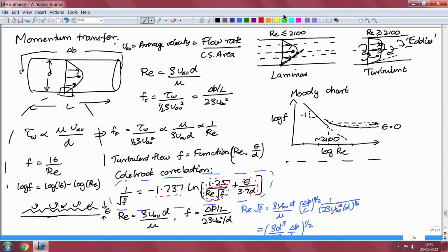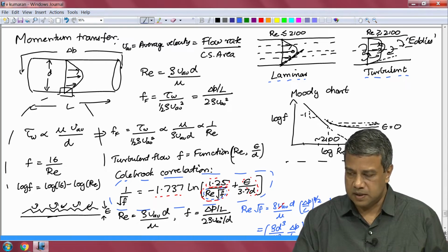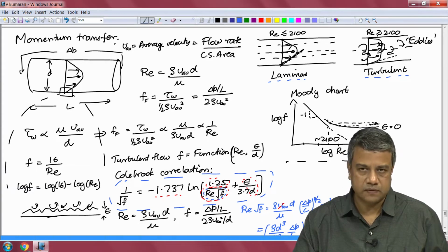In the last lecture, we were looking at the salient characteristics of the flow in a pipe. One of the central ideas here is the transition between a laminar and a turbulent flow. When the Reynolds number based upon the average velocity and the pipe diameter is less than about 2100, the flow in the pipe is laminar. In a cylindrical pipe, the velocity profile is parabolic and the streamlines are straight and smooth, and there are no fluid velocity fluctuations perpendicular to the streamlines, and transport across streamlines takes place by molecular diffusion.